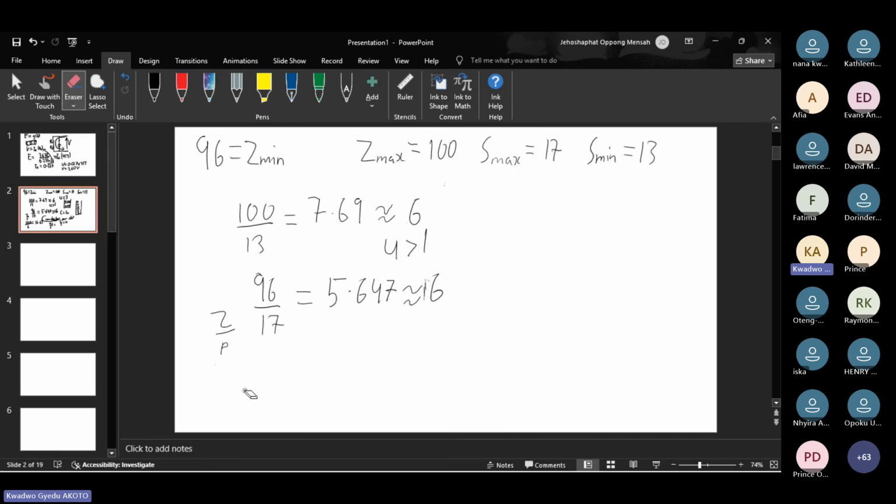Okay, so it went down because if we have a maximum number being 7.69, then that means that we are not looking to go beyond 7.69, right? So if you are not looking to go beyond 7.69, and we know that we have an even number of conductors in our slots, right? Then what is the next even number less than 7.69?